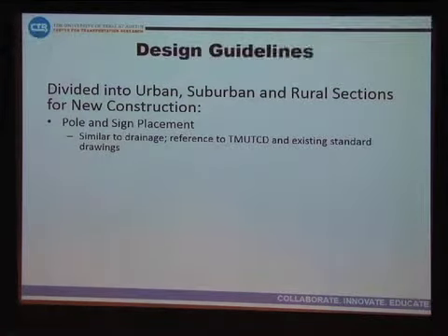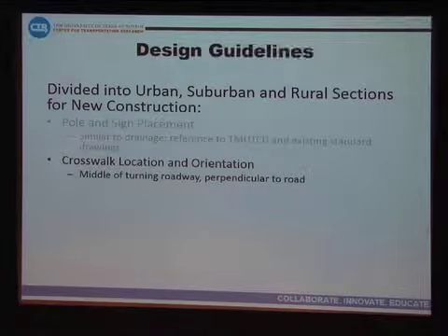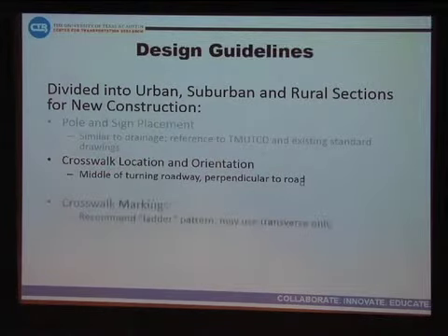Supplemental to that, similar concerns with pole and sign placement, so making sure we avoid those pedestrian walkways. With respect to the crosswalk orientation, we went with the recommendations for putting that crosswalk in the middle of the turning roadway and aligning it perpendicular to the turning roadway to limit the pedestrian crossing distance.